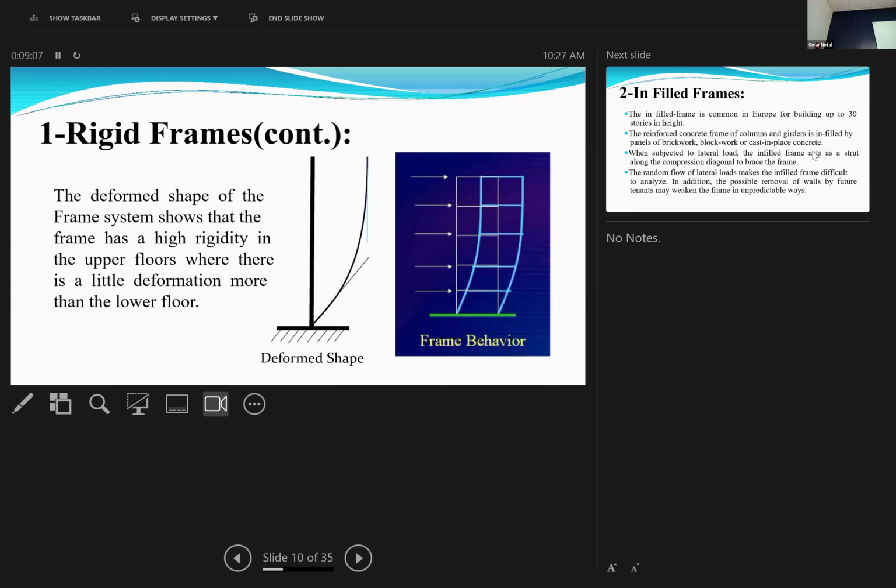So that means this system is very, very efficient in the upper stories, but less efficient in the lower stories, because the lower stories have what we call inter-story drift, the drift between this floor and this floor. This is how we measure the performance of the floor, okay? The more inter-story drift, the more internal forces, and the more steel and construction materials, the more money. So the conclusion is this system is good in the upper floors, not good in the lower floors.